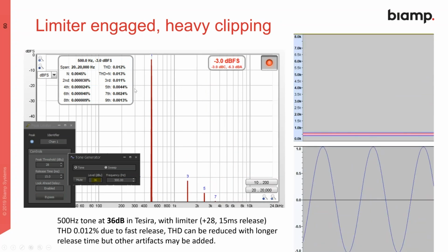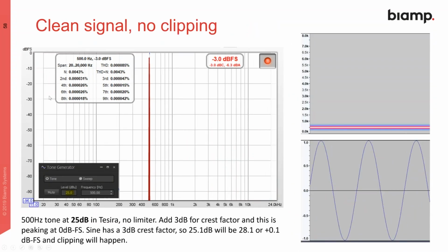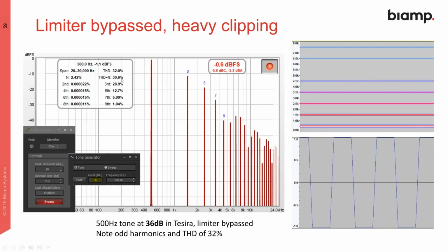And here we can see total harmonic distortion has gone, whoops, scrolled the wrong way. From a clean signal, almost unmeasurable, to the distorted signal, 32% distortion. So huge amount of distortion. We've also gone up to -6 dBFS RMS. So we're actually exceeding digital. We're just kind of this uncorrelated stuff. So you're getting weird output. And these are the harmonics seen in the spectrogram. So we're just getting these additional steady tones that are overtones of the 500 hertz.